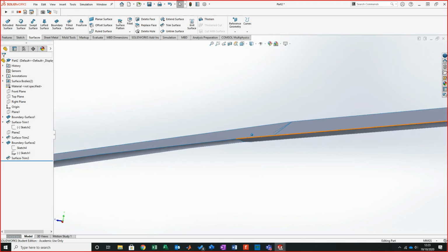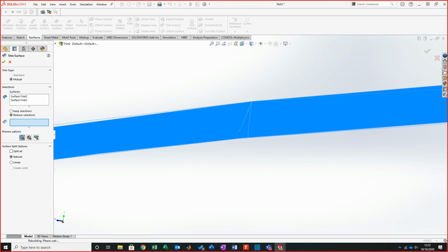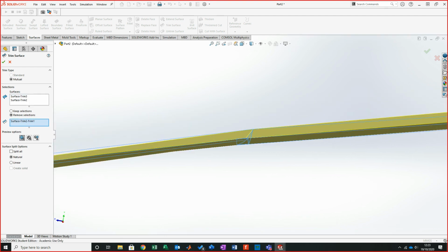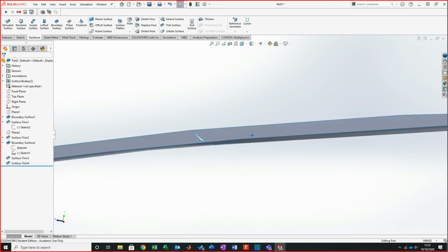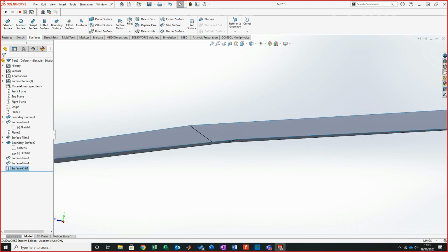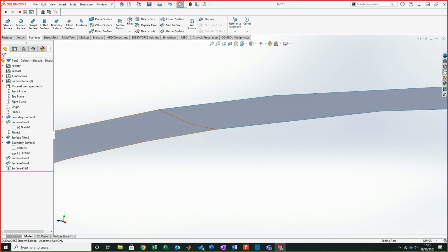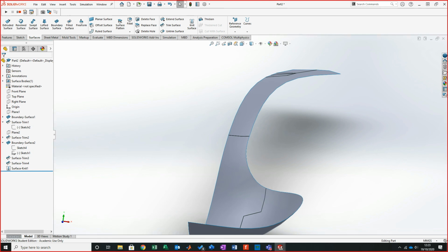We've still got this overlap here as well, so again I'll do the same thing here and here, I'll trim, get rid of that one, let's go there, is that it? Right, so now we've got this tiny gap between it. I'm just going to knit that one and that one, and I'm going to merge the entities together. It should forge them like that. See how we've got this smooth gap between it? It's bang on for what we're after.